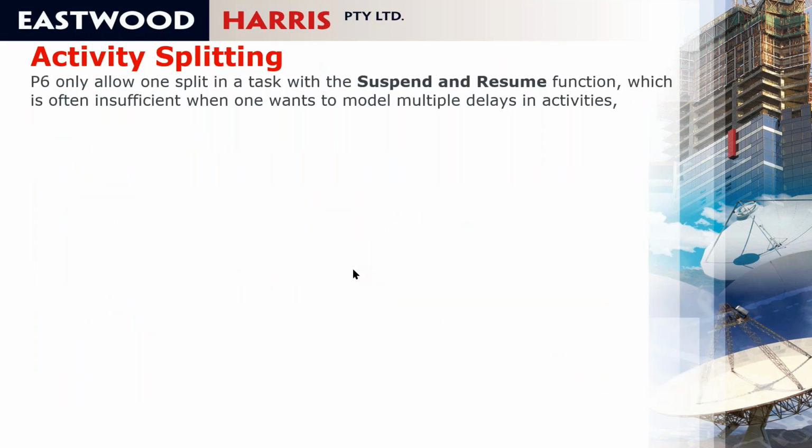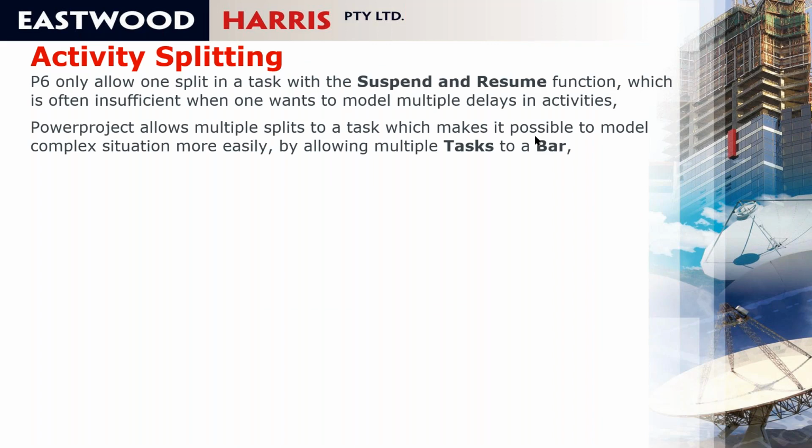Moving on, activity splitting. P6 only allows one split with a suspend and resume, and the intention is the suspend is in the past and the resume is in the future. Powerproject allows multiple splits to tasks, which makes it possible to model complex situations more easily, so you can have multiple splits in the past and multiple splits in the future.